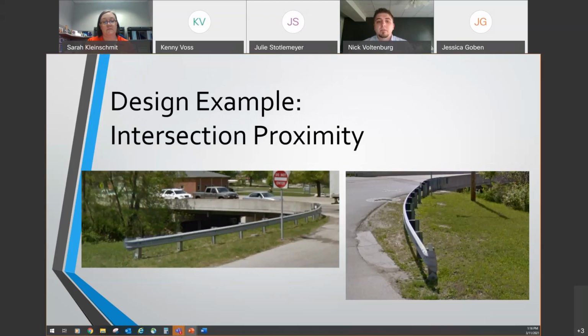So now I'd like to move into a scenario that really highlights this discussion. If you refer to the pictures, there is work being completed on the perpendicular roadway to the bridge that is located at the intersection. The area is very low speed, so the guardrail, when looking at your clear zone limits, is technically out of it. And it's located on a minor route. So per the EPG, it can technically be left in place if it is serviceable.